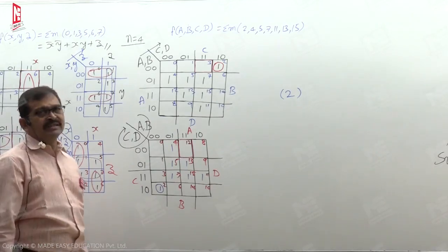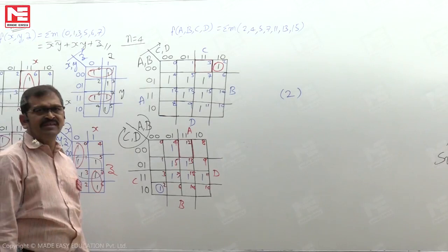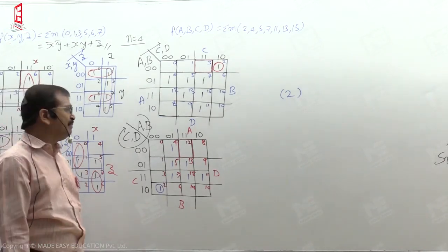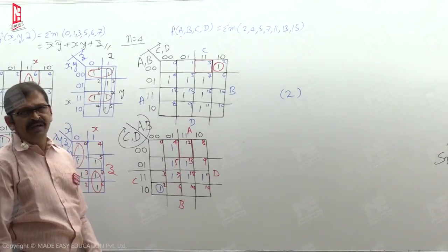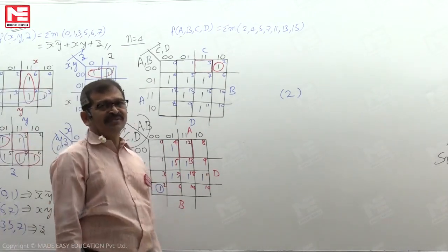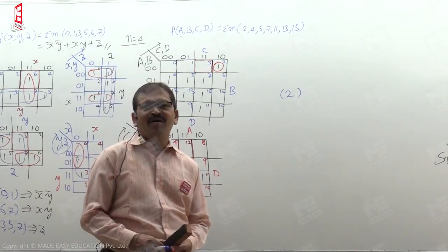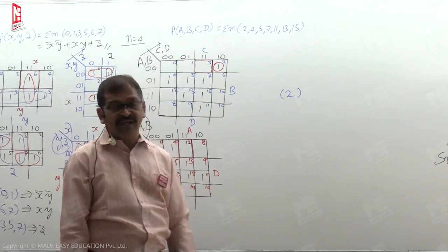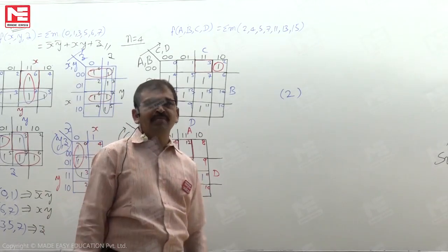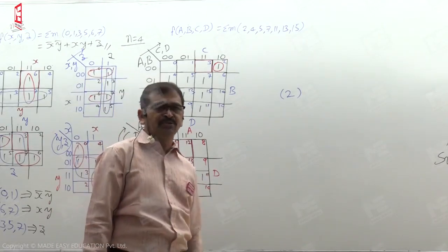Are you having any more independent cells? Of course, the answer is no, no more independent cells. For the remaining cells, for every cell we are looking at, there is an adjacent cell. So only cell 2 is an independent cell. Later we come to the second step. Look to the notes well. The second step, what we said, we need to mark all possible 2-cell subcubes with a condition. It should not come as a part of any larger size subcube.